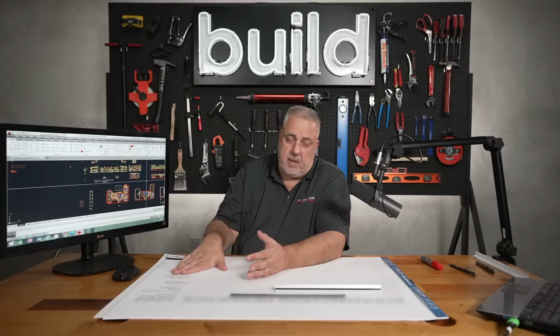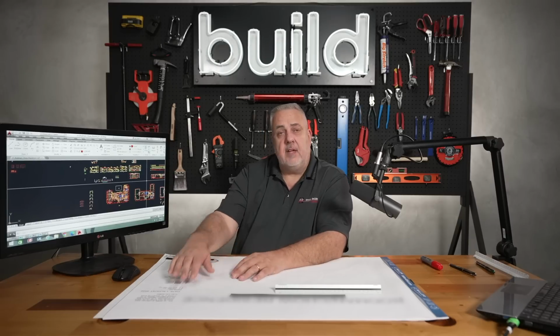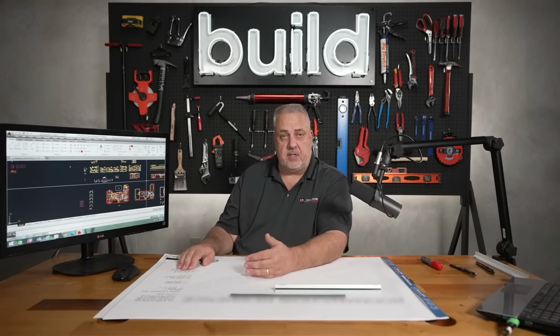And this is something that a lot of commercial architecture firms use. They have a numbering system of their own. This one is obviously smaller scale because it's only a custom residence. But this allows me to come in and say, okay, if I need to develop an additional building section, well, I don't have to renumber any of the sheets. I can just come in and add it as sheet A36, and then that becomes building section GG, and it gets inserted, and my drawing list doesn't change other than the simple addition of that number.